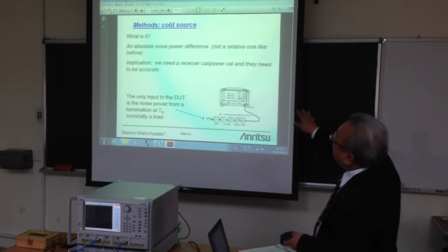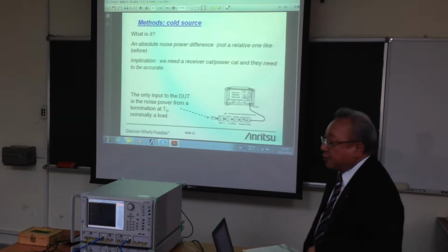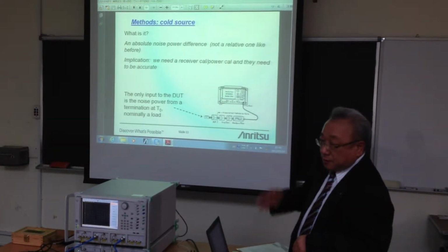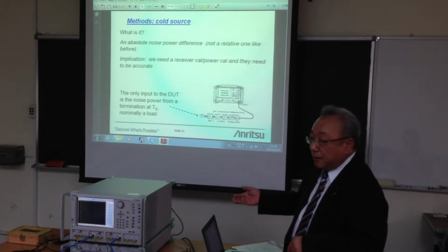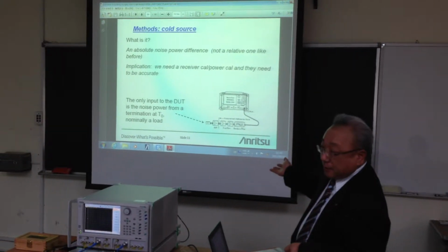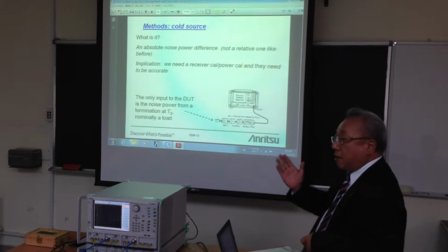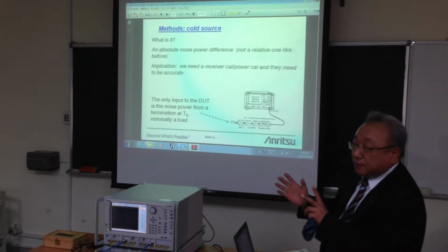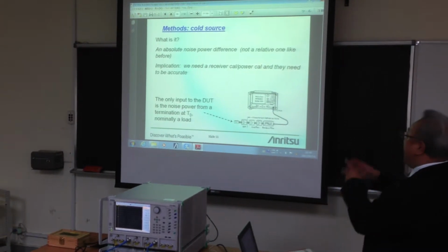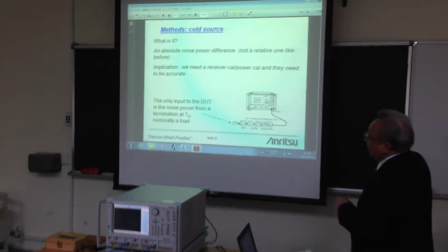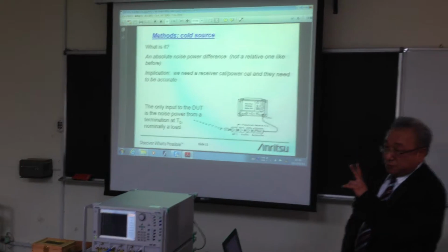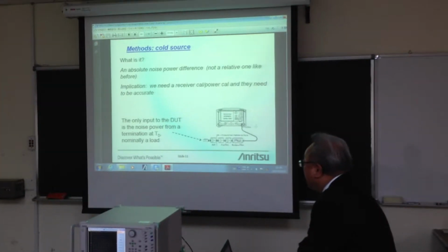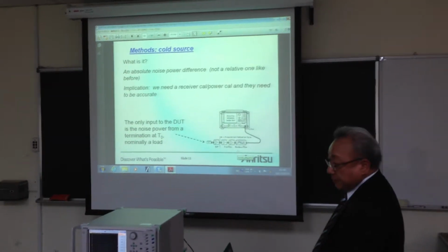Because the VNA or the spectrum analyzer down converts to measure any signal internally, the local generator can produce imaging. Then sometimes an illegal signal is applied to the IF port. Such spurious is eliminated by an external bandpass or low pass filter.